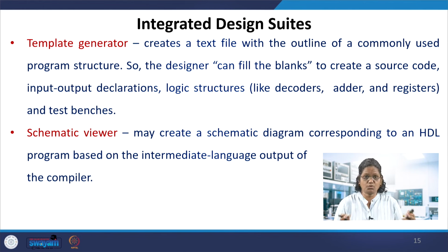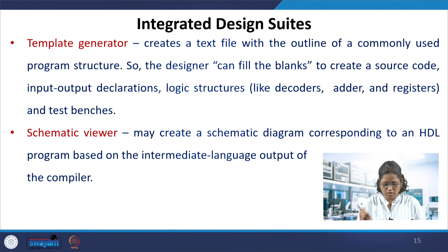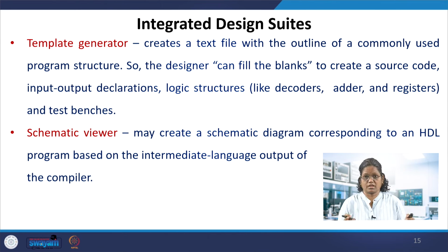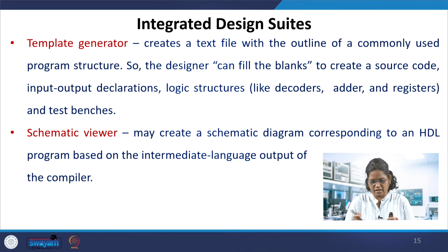So the schematic viewer is also part of this design suite. It creates a schematic diagram which corresponds to the HDL program, what it describes. So there are blocks, and these blocks are connected. It depends on the code. This schematic viewer shows the blocks which are needed for the program, and it shows the intermediate language output of the compiler. So after the compilation output, you can see the blocks connected, which is equivalent to the design you have done on paper, like your digital circuit.